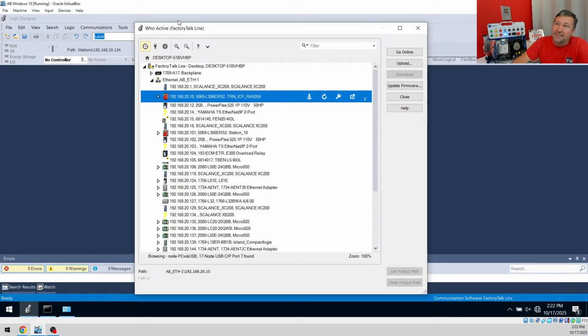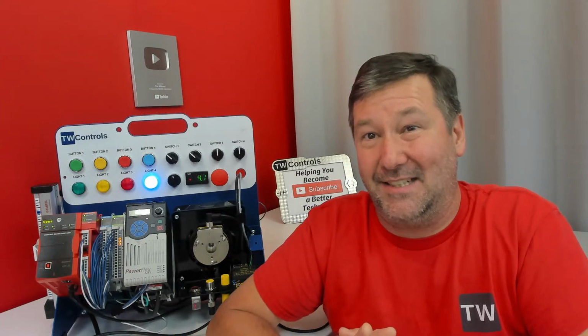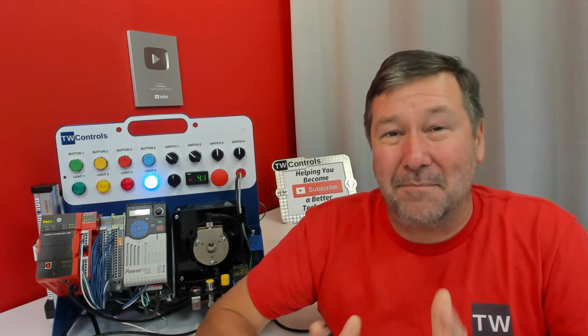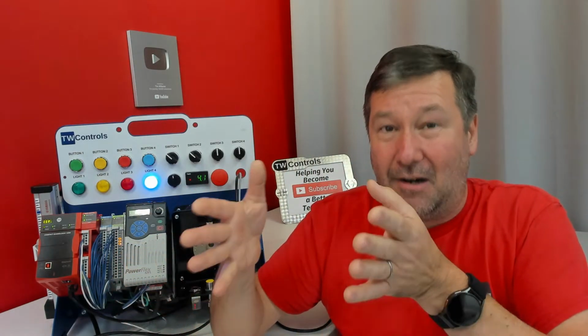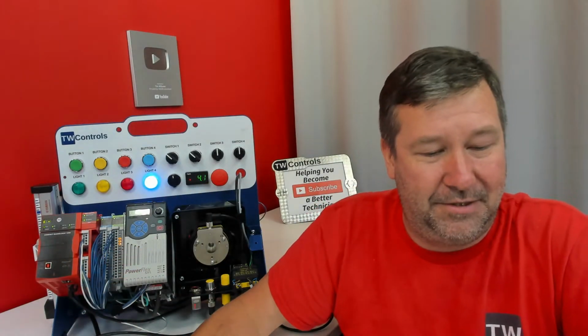First of all, this is FactoryTalk Linx. And for the most part, when should we use FactoryTalk Linx? Pretty much whenever we're using Ethernet or USB, unless Rockwell software tells us otherwise, is what I always tell everybody. So in modern applications that we should do. Now, if we get into RsLinx 5000, that's going to be older than FactoryTalk Linx. So we're going to have to use RsLinx. So I want us to see that one too.